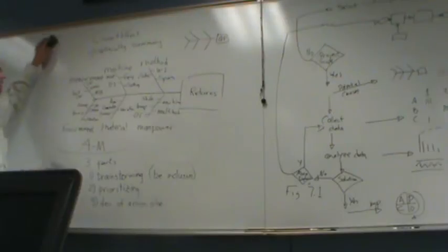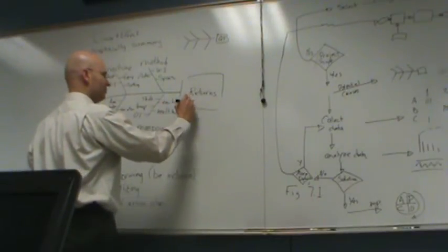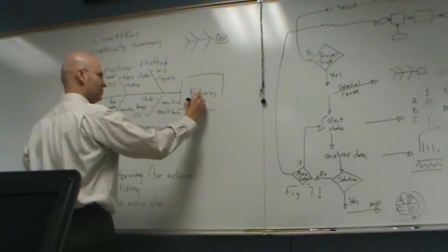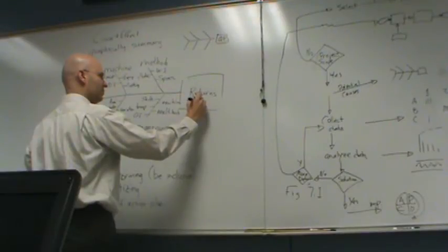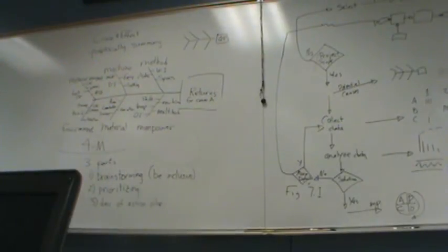So that's a cause and effect. So before you erase it, if you're looking through, we've just brainstormed all these multiple items as things that could cause returns. When you do this on a specific example, you might have a little bit more detail than just returns. You might say returns for blank. It could be missing part, damaged part, non-functional part, intermittent. And you'd go through these different categories that you've listed, and normally you're keeping in mind as you investigate that failure mode.